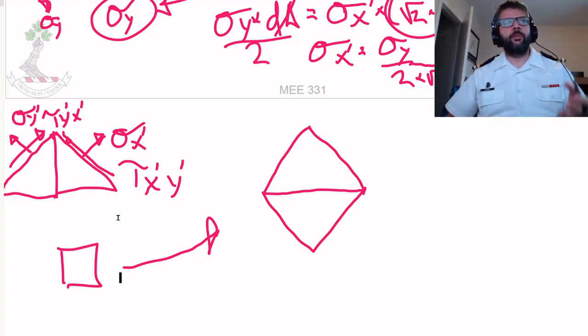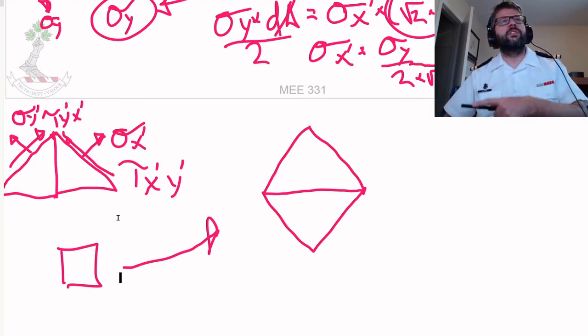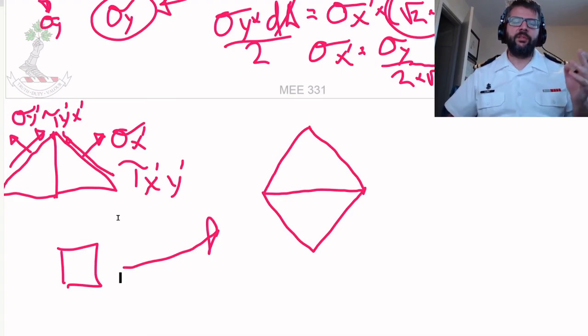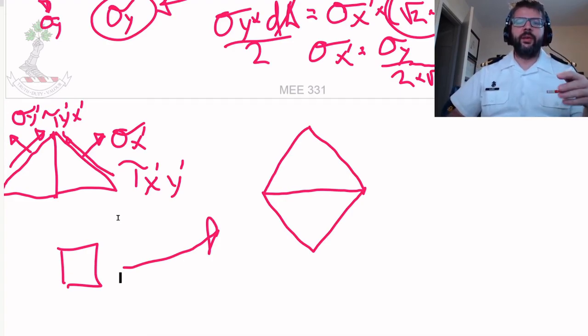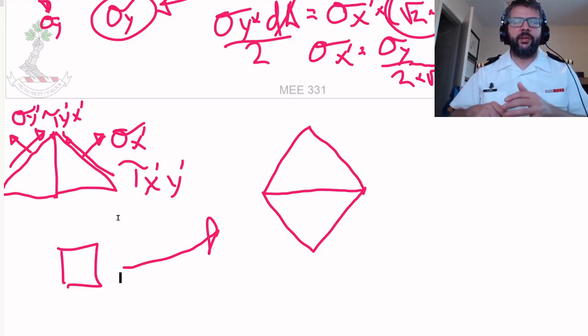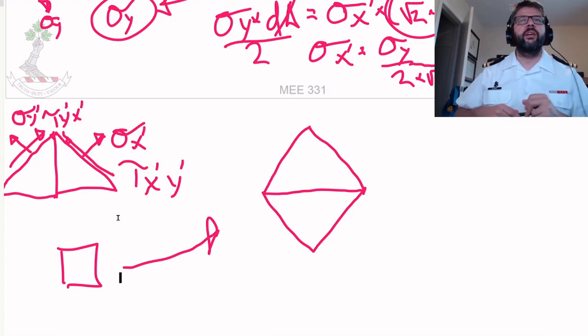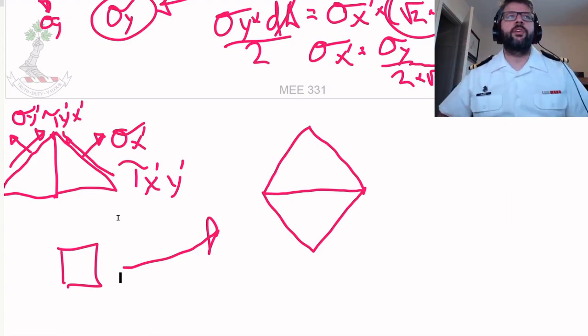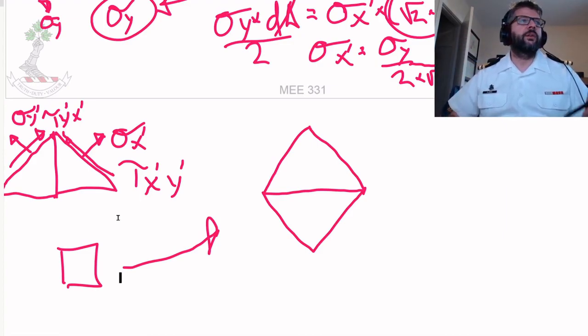We call that the transformation to the principal stress, and those are used extensively when we are trying to figure out, is this component going to fail? Because all of our failure criteria that have been developed allow us to plug in the principal stresses that we calculate to figure out, hey, is this thing going to fail on us based upon these three numbers, instead of having to use the 6 independent numbers that we would have in a stress tensor otherwise.